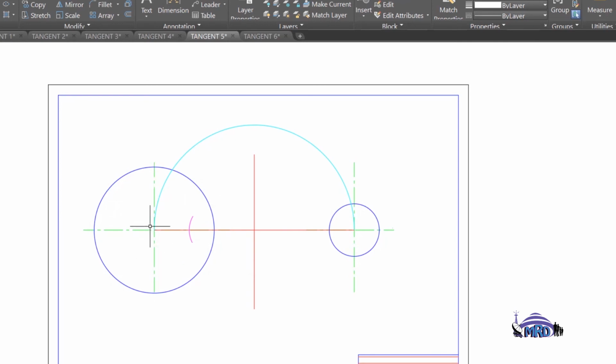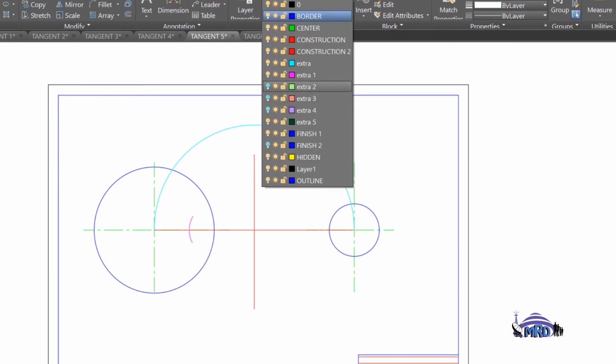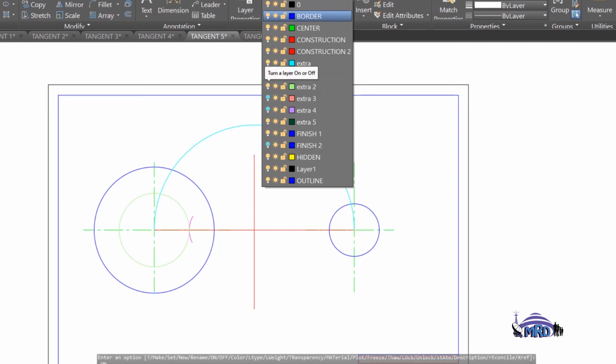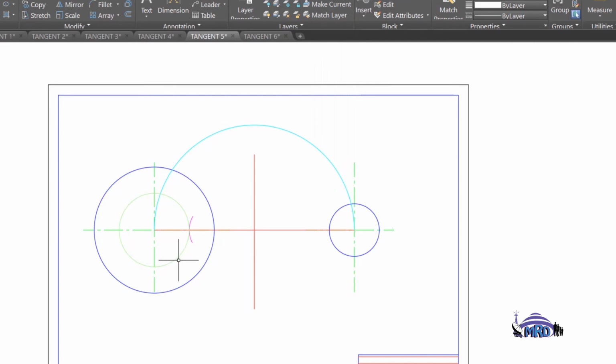So that now gives you the opportunity to produce another circle on this drawing. That circle will be from the center of the big circle to the point where you marked off the 25 millimeters. So if you took away then 25 from 60, you would be left with 35. So the radius of this new circle that I'm representing here is 35 millimeters. This new circle will be used to give you the normal for the tangent.